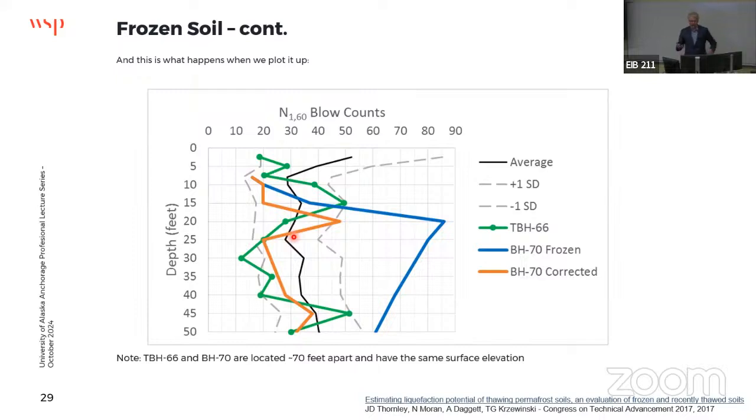And so when I'm looking at the soil, it's sands and gravels, right? But when I'm on the thawed side, I see these sands and gravels and they're really wet. I don't know how wet because I lose some water out of the bottom with the sampler. But when I sample over in the frozen area, I get all the water and all the soil. And you can see that you've got some ice, right? Now ice is filling up space that the soil could be, because it's in a fairly loose state.